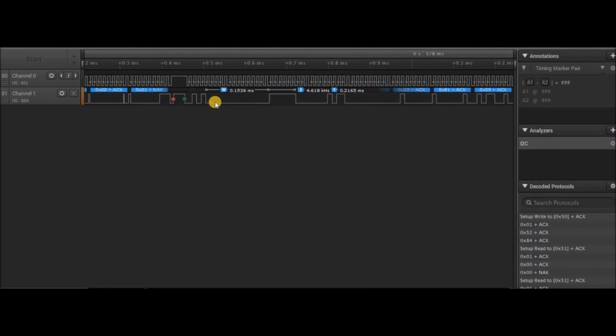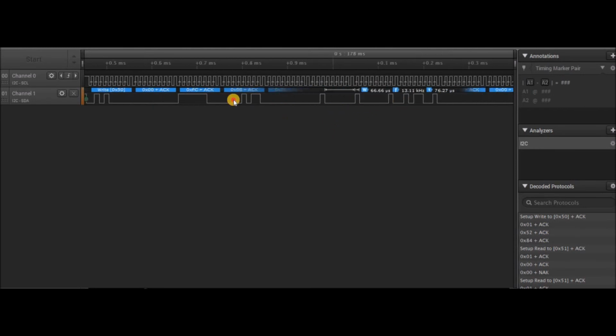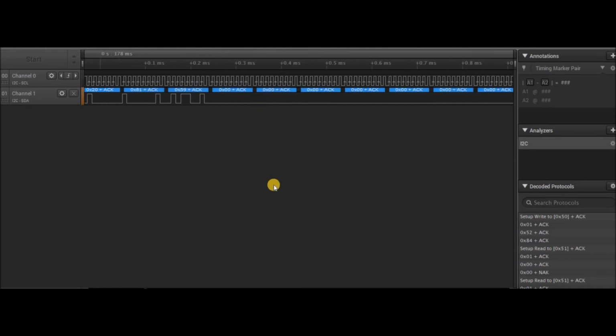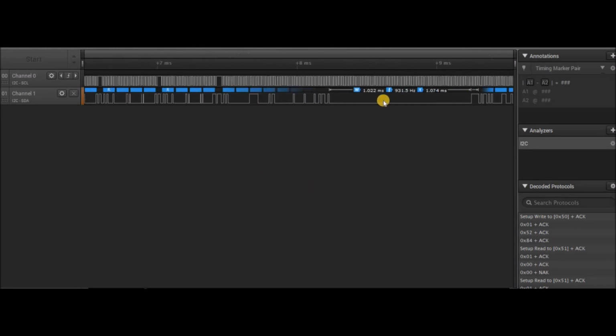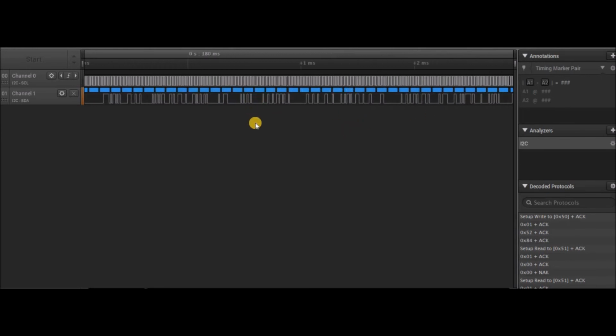So we can see a block of software being copied here. We see a write, we see the command 0, which means write to flash, and then we see what looks to be almost random data because that is the code being copied. Here we get a bunch of zeros, but otherwise it's fairly random, and we copy this in blocks.